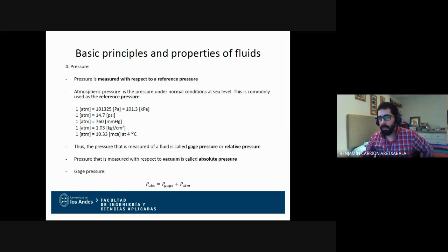Okay, so within the fluid, we're going to talk about relative pressure, relative to the atmosphere. We don't normally mind much about the absolute pressure. But if we would like to measure from an absolute zero, that absolute zero is the vacuum, which is outside the atmosphere, and then you would need to add the atmospheric pressure to your values. As you know, the atmospheric pressure changes from location to location. It depends mostly on geography, but it also depends on the weather.